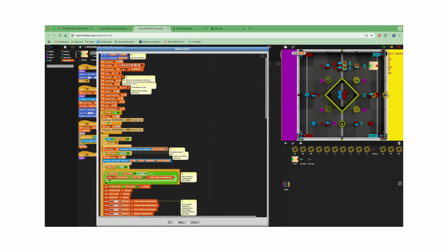The way that it actually finds the best route is by solving something called a VRP, or a vehicle routing problem. This is the same thing that UPS or FedEx do when they're delivering packages. How it works, for us at least, is it calculates the amount of distance the robot has to move and the degrees the robot has to turn. They add these together right here, and that's how we get our total cost. We can compare routes to each other based off of the total cost of the route.